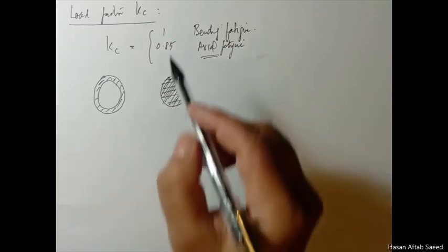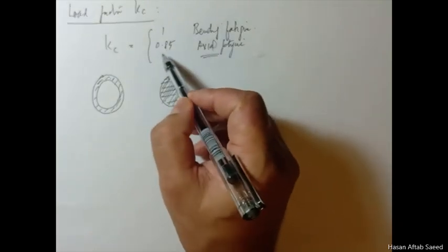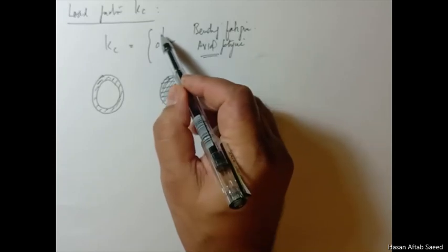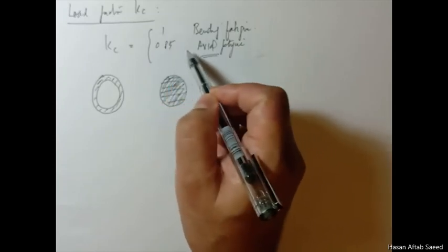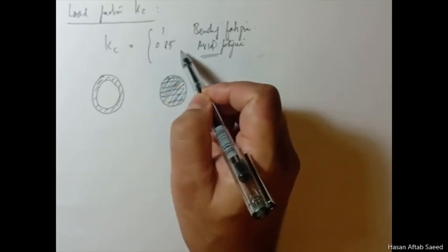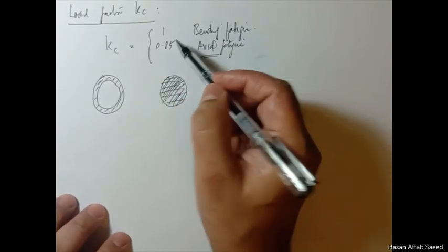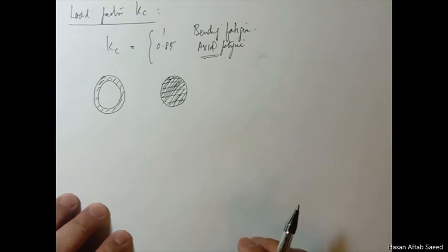So although by first look you may feel that because it reduces the endurance limit and this doesn't, this is less, this is more dangerous. Actually it is not, but still when we are doing this, there can be cases where it can be very dangerous, so we'll be using this correction factor.